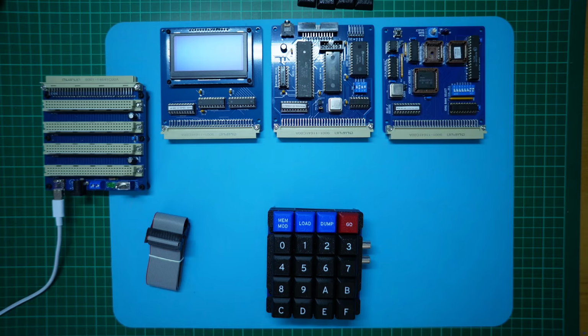The main reason was so that I have both the Dream 6800 code and the Assist09 code in separate banks. So while it's on, I can just hold the reset in and switch across between Assist09 and the Dream 6800, which enables me to use Assist09 to transfer files during development.